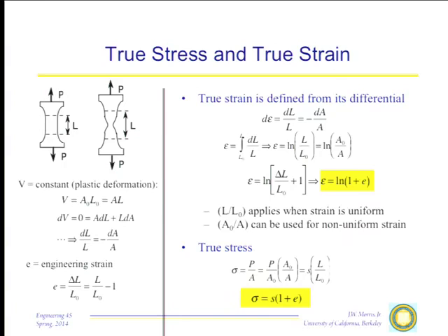So the true stress is equal to the engineering stress times 1 plus the engineering strain. So there's a simple relation between the two. The true strain is a little tougher because the sample, of course, gets longer, particularly in plastic deformation. And when we get past the ultimate tensile strength, where plastic deformation becomes unstable and the samples begin to neck, then we have an unusual and even more difficult situation to deal with, where the strain is actually changing from point to point within the region of deformation.